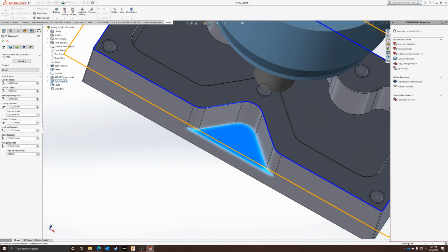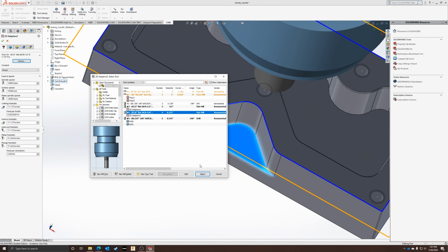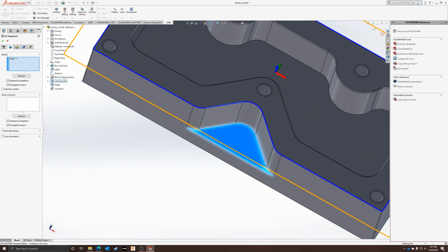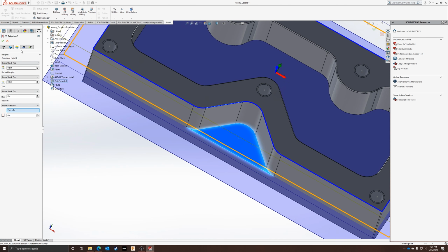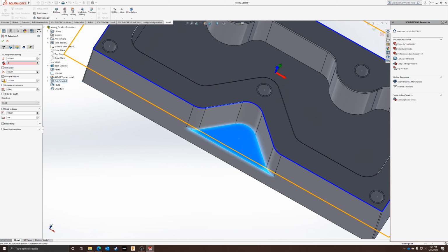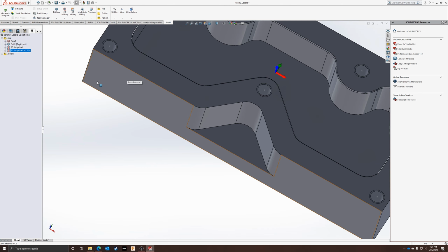They're not linked, so I can't ripple the effects over, which is why a lot of 2D adaptives is not as fun as a 3D adaptive. We'll talk about that in a second, right? And then once again, 0.07 times 3/8. Done. 0.9 times 0.75. And then all this is okay. We said, oh, let's make this smaller. It doesn't matter that much as long as the minimum engagement is smaller than the optimal, right? Because I can't have a minimum engagement larger than what's best. Then it just is pointless.